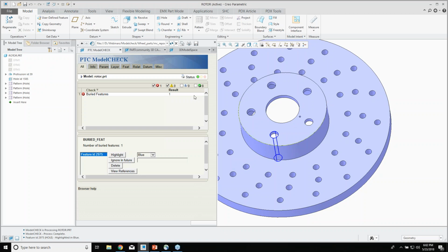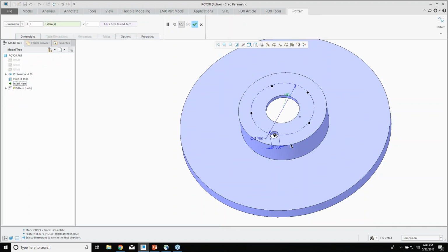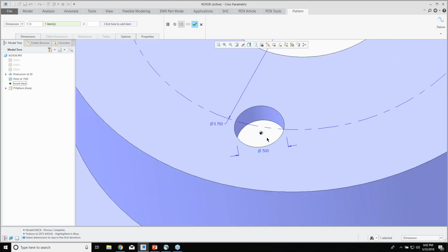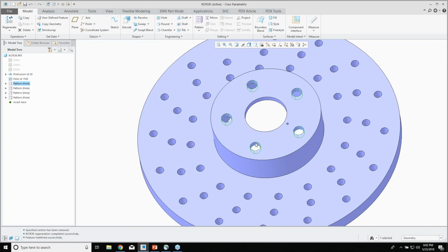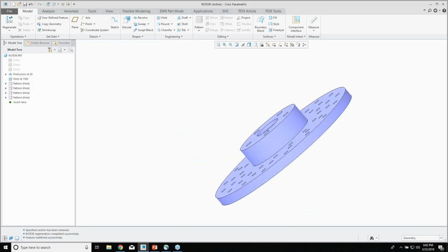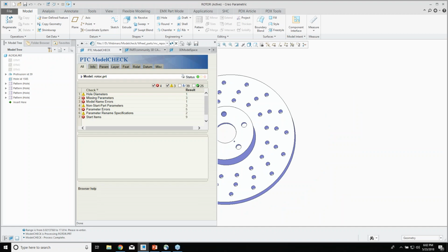Okay, so let's see what did I do actually. So if I edit definition this, so see, I've made it 6 members. It just added another member on top of that. Okay, so now I know that's not right. So I need to change that back to 5. Okay, so now if we regenerate again, now model check says everything is fine. Then I want to show you something else. If we run interactive, it will give me certain errors now.